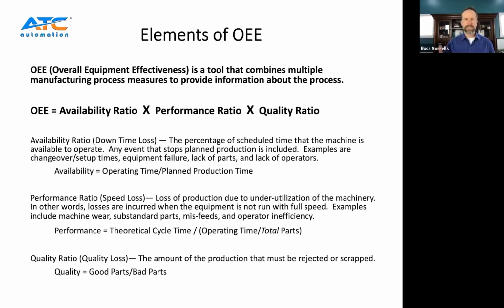So let's talk about that right quick, Bob, if you will. So we've got 24 hours in a day. I can't remember, 28,000 seconds in a day or something like that. But then based on the amount of lunch downtime they have, right? So that's planned. And then your breaks that you're going to have on top of lunch, and then maintenance downtime would be calculated in that. So some of it's planned and some of it's unplanned, but all of that goes into calculating the availability ratio.